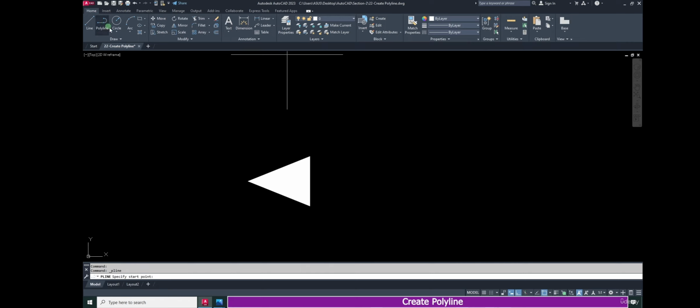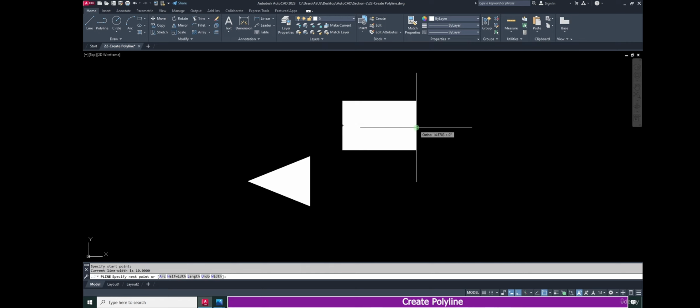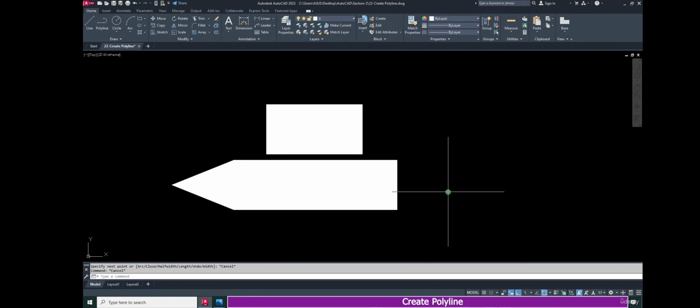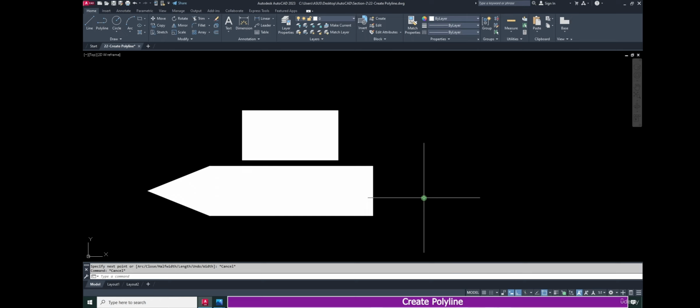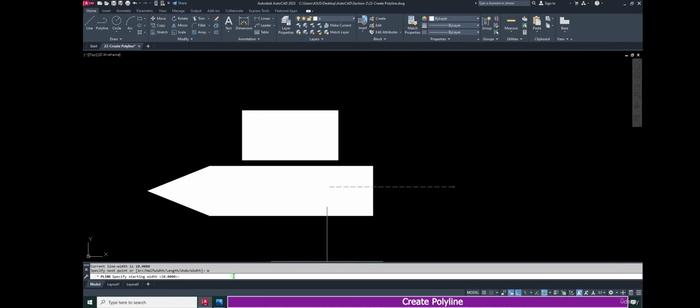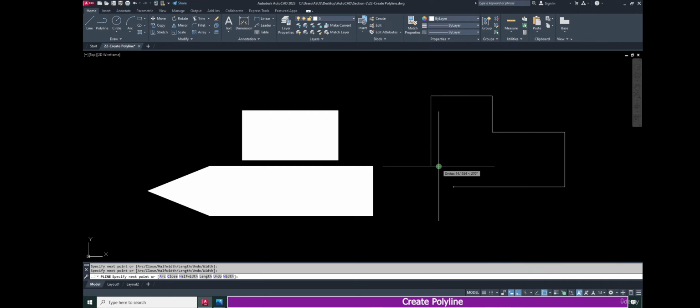Again I go to the polyline. Now I create line. You will get it this ending width. This one width is 10 mm. Press escape key. I just go to the polyline. If I click here, you can see you will get it this same width. But we need to go back to normal polyline. Go to the polyline, click any location, select here width, make it 0, press enter, again 0, press enter. Now we can create normal polyline.